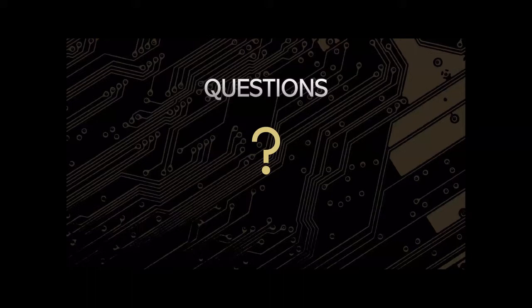All right, from Torch, what's the best practice for solder paste definition? Do you need the designer to provide a stencil layer in the Gerbers, or do you prefer calculating the sizes on your side based on the raw pad size? This is similar to our last one, so that's a question I would like to answer. What we are actually looking for is the paste Gerber, and what we prefer is a 1-to-1 ratio with the copper pads. Once we have that, that's the minimum information that we need.